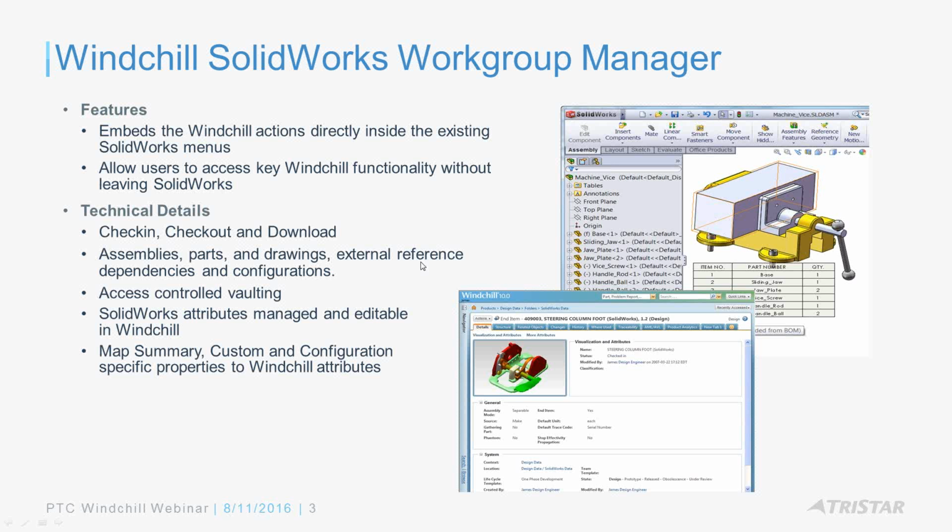The support for some SolidWorks specific features, which I'll go through a bit later on, such as configurations and toolbox and weldment assemblies, is also part of the Workgroup Manager. Any new feature that the CAD vendor will add, typically PTC will support it within a few months. So if you keep your PDM system updated, yearly, every half a year or so, with service packs, then you'll be able to take advantage of all these new features.